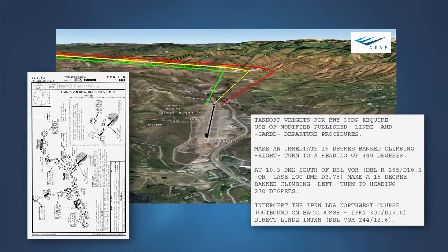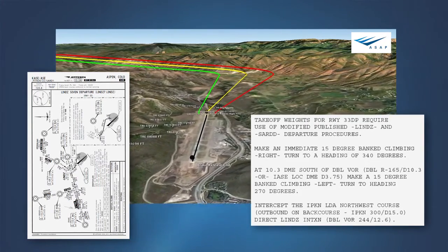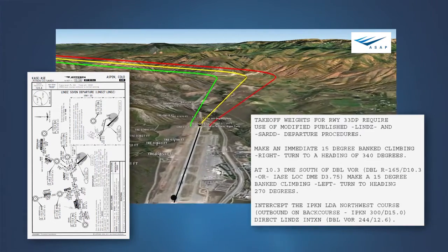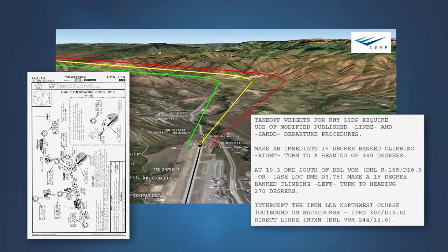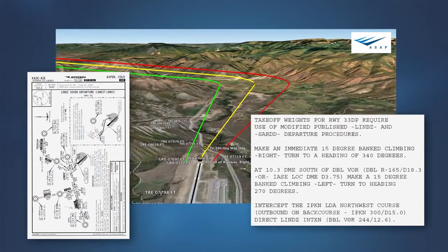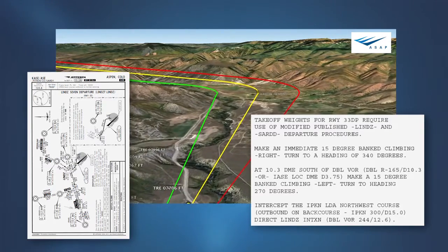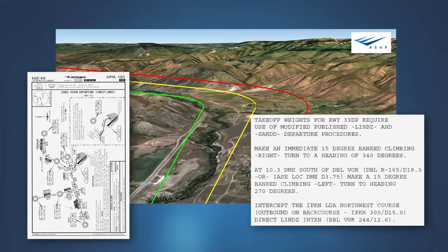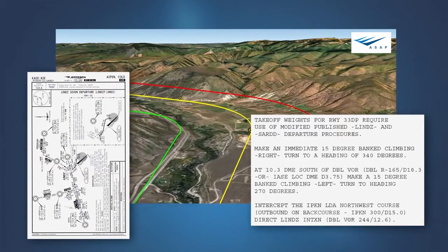However, modifications may be necessary to identify the start of any turns using precise geographical references instead of the altitude crossings that are frequently used on SIDs and ODPs. If it is not already available, it may be appropriate for the operator to request an engine failure procedure that does align to the SID or ODP to the extent necessary for the airplane to reach the IFR en route environment. As we saw at Aspen, this may involve the use of a conveniently located holding pattern.